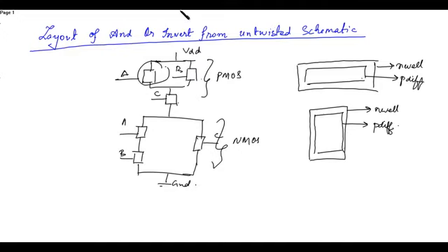Okay, now you have to draw the layout in this form. So now let me clear this. The PMOS P1 and P2 were in parallel, so we will exactly draw like that.